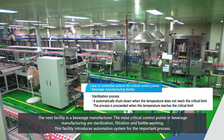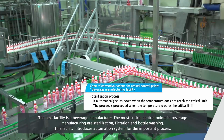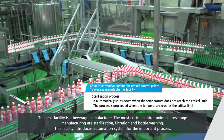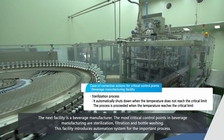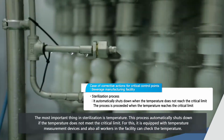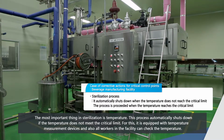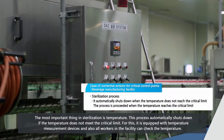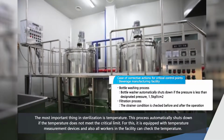The next facility is a beverage manufacturer. The most critical control points in beverage manufacturing are sterilization, filtration, and bottle washing. This facility introduces an automation system for the important processes. The most important thing in sterilization is temperature. This process automatically shuts down if the temperature does not meet the critical limit. For this, it is equipped with temperature management devices, and all workers in the facility can check the temperature.